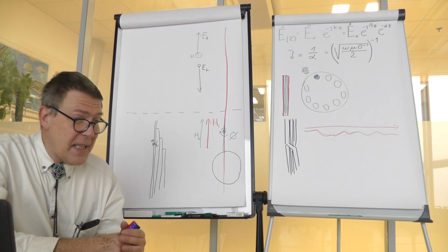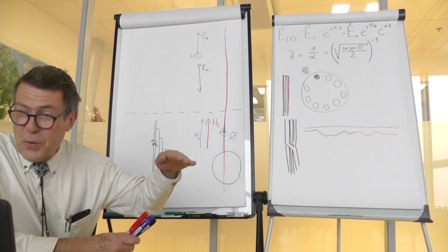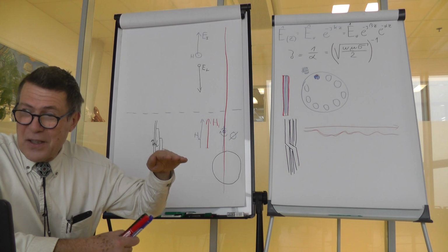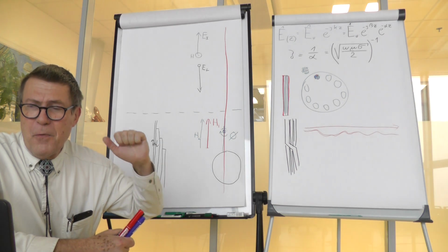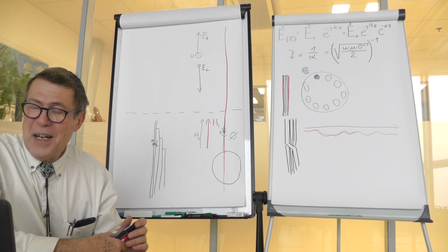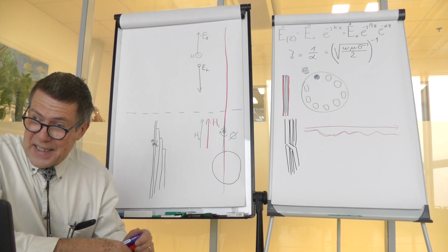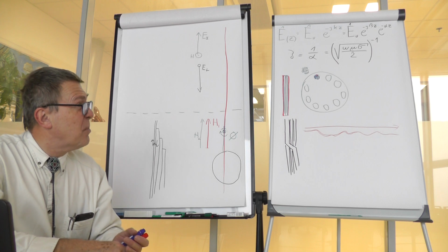So the acids would destroy the surface, and once you have the surface which is not purely silver, the acid components with silver form something which is only semiconductive, and you have very high losses. So it makes sense not only to polish the surface, but also to protect it by a layer which does not let the oxygen and sulfuric acids and other components of the atmosphere get in. So that's an important point to learn.